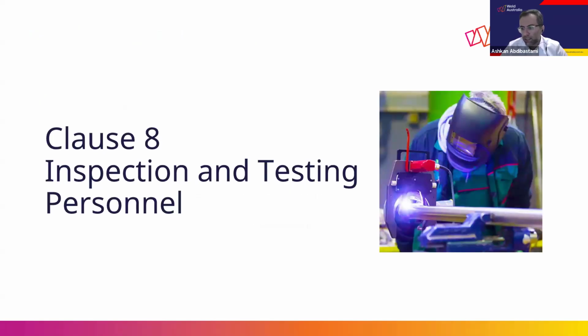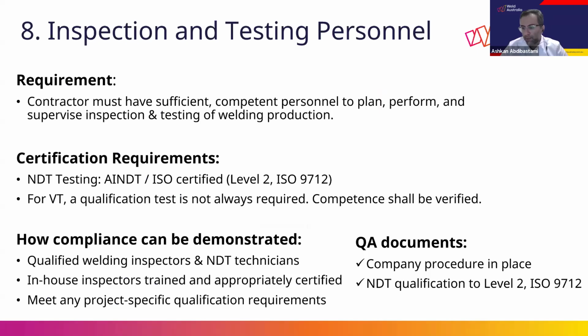Clause 8, inspection and testing personnel. Manufacturer must have enough qualified staff to oversee welding, inspection, and testing. So NDT technicians need to be certified to ISO 9712 level 2 through AINDT Australian or BINDT British one or equivalent.